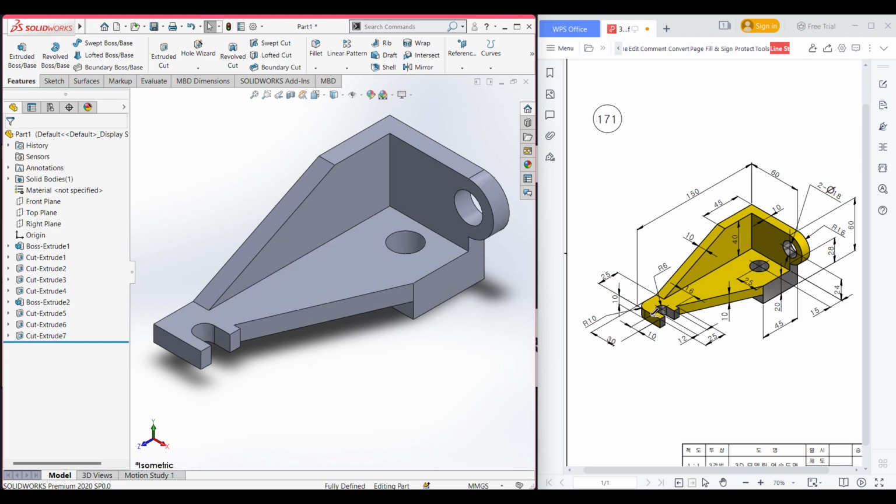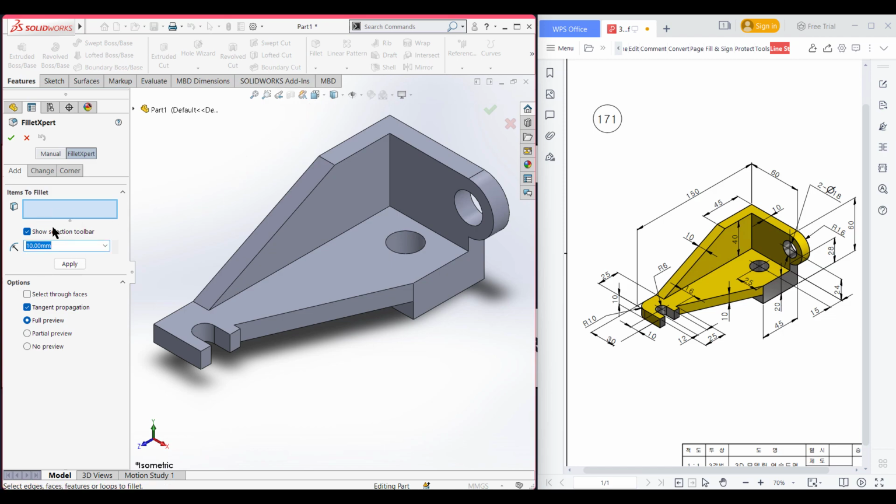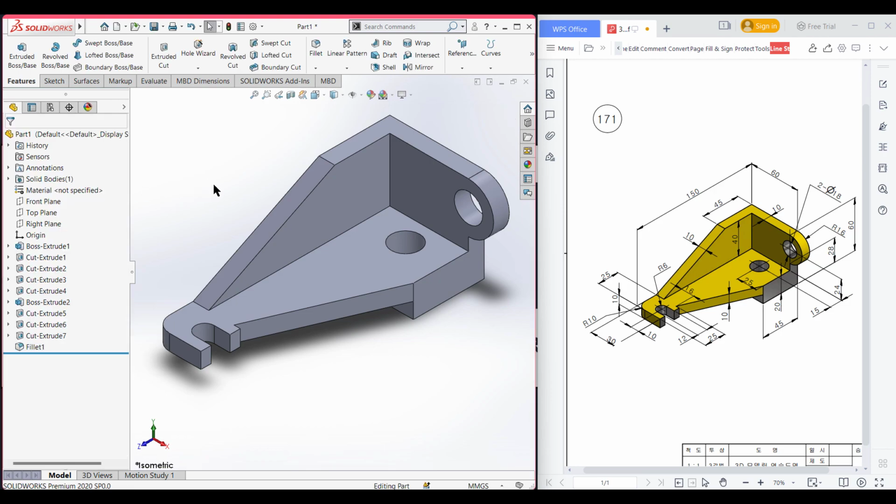Now if we go back to our sketch, we have a fillet here, and this fillet has a radius of 10 radius. Okay, so I am selecting the fillet option from here. Now dimension it to 10 radius and selecting this edge. Now press OK. So this portion has also been done. So as you can see, we have drawn our 3D sketch.